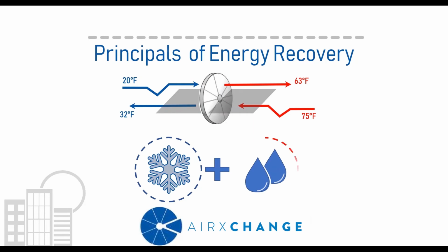And secondly, you need a source of liquid water. Now, one of these items really isn't available during most normal winter operating conditions, and that's liquid water. And that's due, in fact, to the energy recovery process, or the humidity transfer process, being transferred through the method of adsorption. Adsorption and conversely desorption is the transfer of water in the vapor phase.